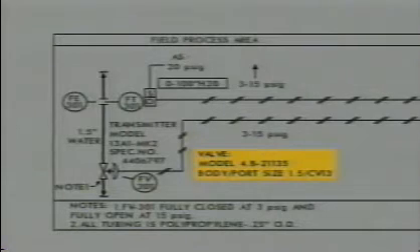The information is located near the instrument or component to which it refers. Those notes that are too long to place on the diagram refer you to a number in the General Notes section, as we see here. The note refers you to Note 1. When you read Note 1, it gives you specific information about the valve.